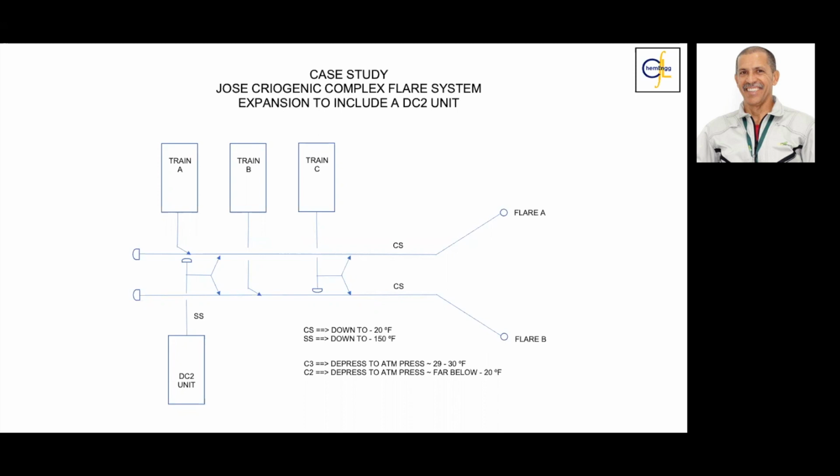And then the recommendation in that system is, forget about the carbon steel impact test. Design everything for stainless steel. And then they say, well, but it costs more money, blah, blah, blah. Okay, but we're talking about safety. If you want to do things well, do it well up to the end, because the simulator isn't the reality.